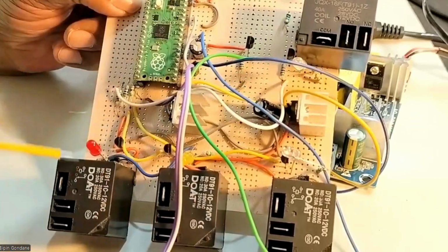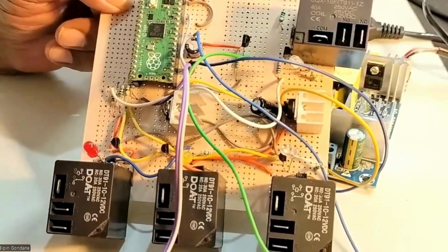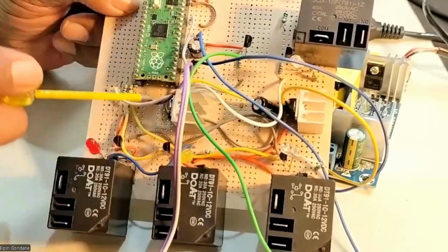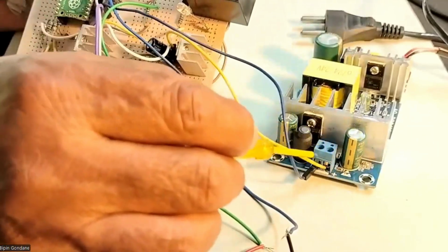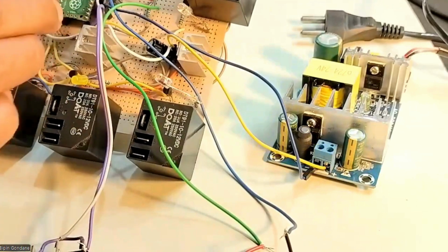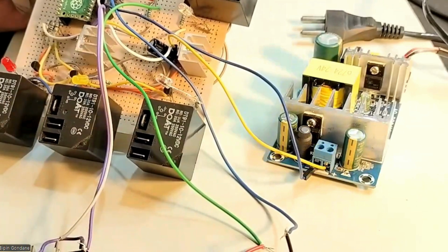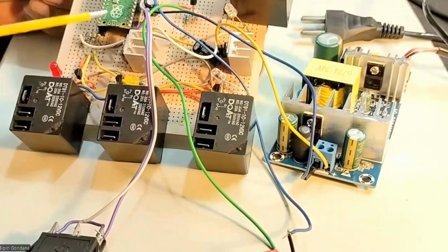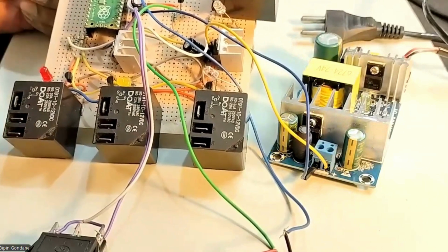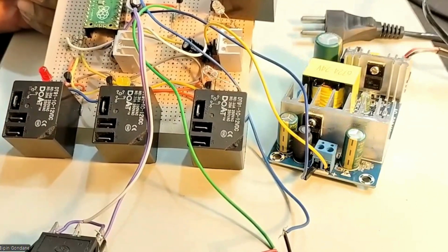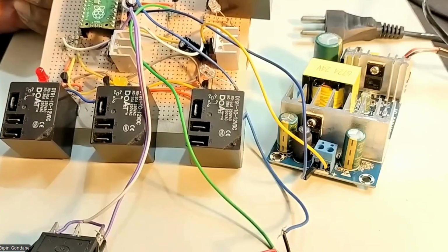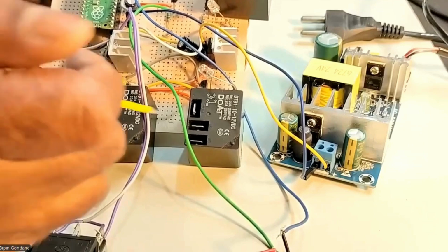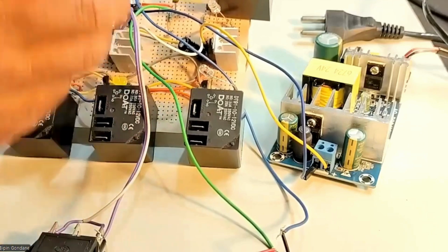The transistors and relays will work on 12 volts, and the input to both the 5 volt and 12 volt, we are giving 24 volt from the power supply. These are the 2 outputs, which are 24 volt. The same output from here will be given to the lights also. Please remember, Puffin means not only pedestrian crossing, it has to indicate the stop indication to the traffic light also for the vehicle side. So stop and all that has to be indicated. For that purpose, I have given these main relays.